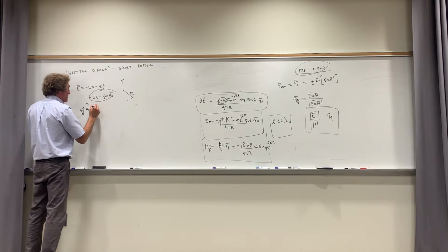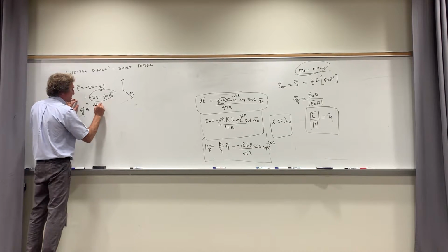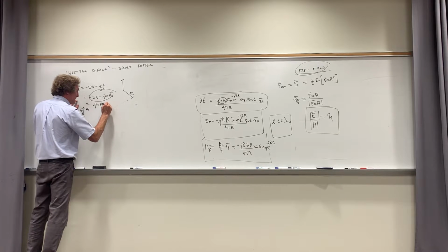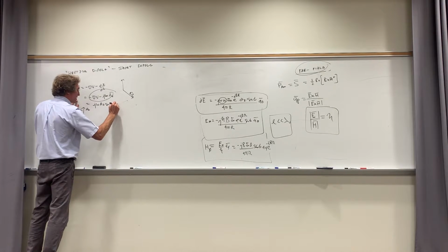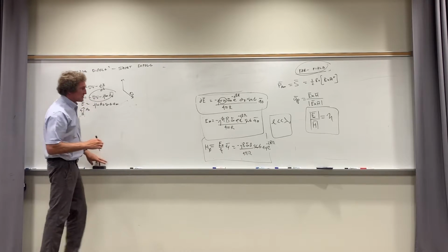Well, sorry, that's what I forgot, the minus there. So this will become j omega times A_z, and that's positive, times the sine of theta in the A theta direction, and that will be the E field. I'm sorry, it is positive.